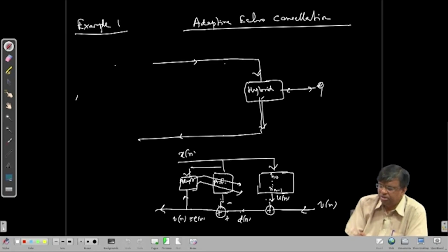So, at any time the coefficients here will not be exactly equal to H0, it will be fluctuating around a particular H. Say you consider the corresponding coefficient H0 here, because it is adaptive, it will be fluctuating around H0. So the mean of the fluctuation is H0. It will not be H0 always, since it is fluctuating, and the same for all the coefficients. The filter output will not be exactly equal to Un, there will be some error, but the error will be small because by adjusting mu we make sure the fluctuation range is very small.